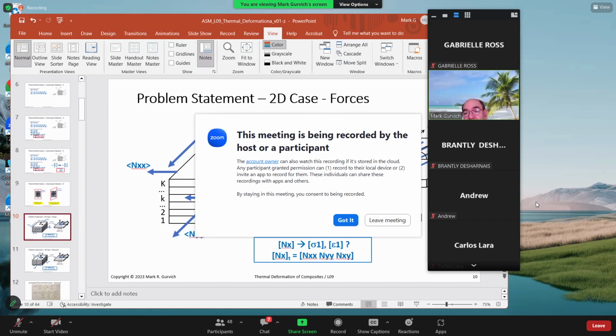Sometimes in papers or discussions people call it thermal load. It's not a load in the traditional sense of forces and moments, but it is still a factor that could generate stresses and strain and, most critically, damage or failure. This is why it's called thermal load. So this is the two-dimensional case of a laminated system.